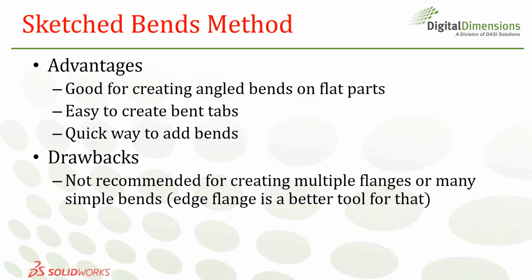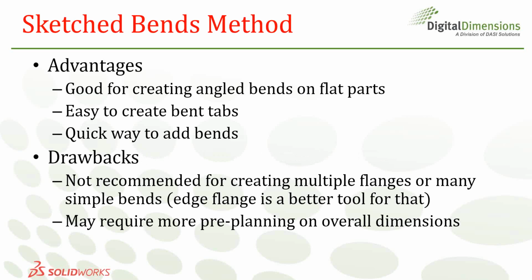Some of the drawbacks I thought were, I don't really recommend it for creating multiple flanges or many simple bends, just like I just did. So the edge flange is a better tool for that overall. It's just a lot quicker and easier to use and has more control as well. This one, like I showed before, may require more pre-planning on your overall dimensions, so you need to account for the flanges initially. So if you have a part that you want to be 125, but you want the flanges to be 25, you need to add those in and pre-account for that type of stuff. So it just may require a little bit more pre-planning, right?